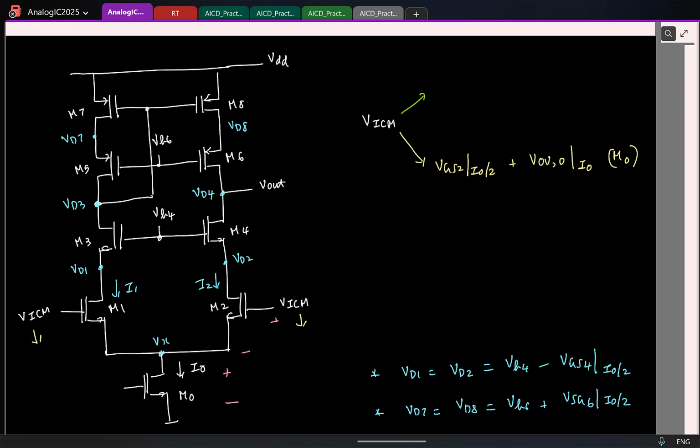Let's look at the upper end. Now I'm increasing the gate voltage. Which transistor can go out of saturation now? Yeah, I'm increasing the gate voltage of the NMOS transistor, which means this can go out of saturation. What is the maximum the gate voltage can go compared to the drain? Yeah, remember the maximum gate can go one threshold above the drain, right? Similarly, the drain can fall one threshold below the gate. It's easy to remember. So the maximum gate can go one threshold voltage above the drain voltage, and I already know this drain voltage is this fellow.